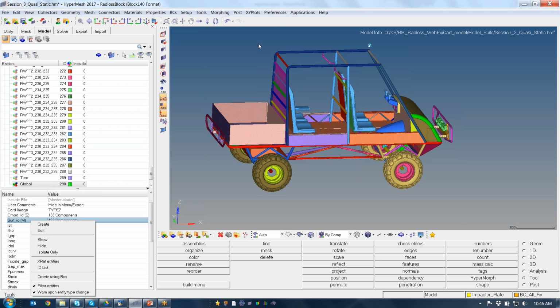You'll get one more pop-up window, through which you can directly add the components. That will be used in many instances. Let's say you have applied the initial velocity and you have forgotten some of the nodes or components. You can do that. The same thing applies with the loads and boundary conditions also. So that is fine.